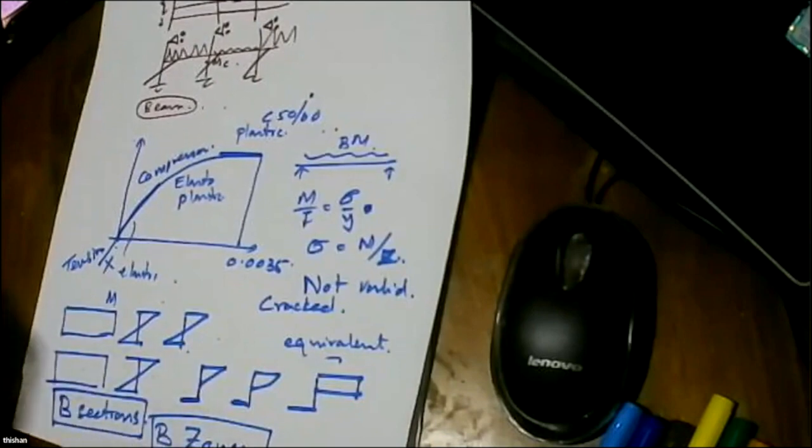Then we started looking at it again, investigating why the geotechnical engineer had given such a low capacity. Then we found the geotechnical engineer was correct. There's a big problem in that particular site. What is the problem? The rock has cracked vertically.